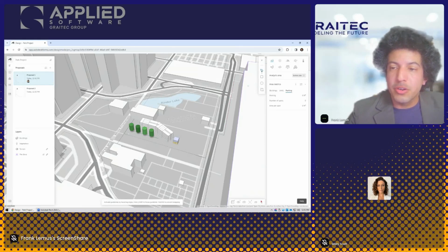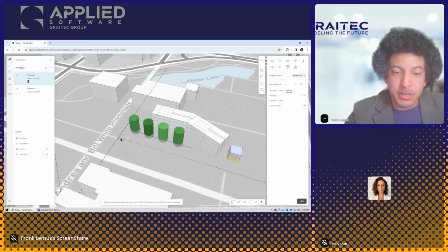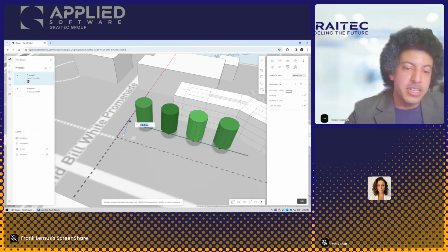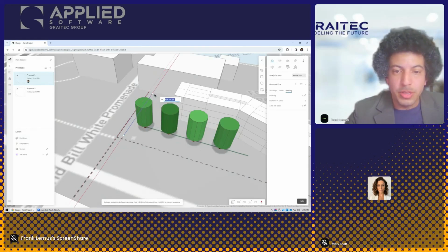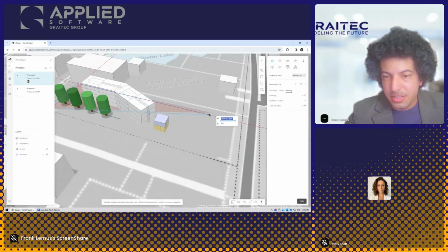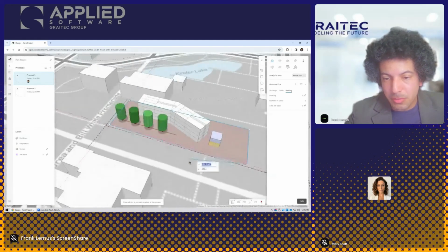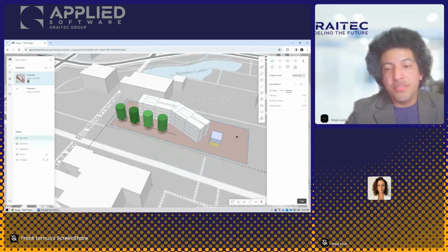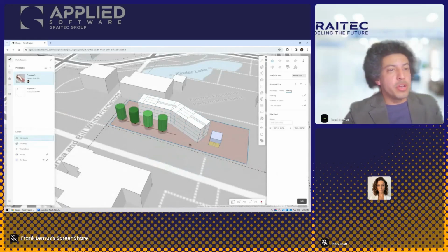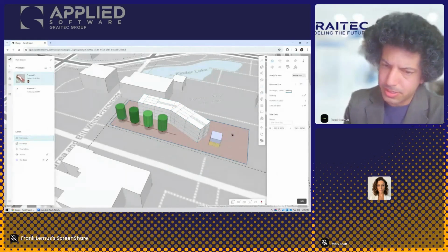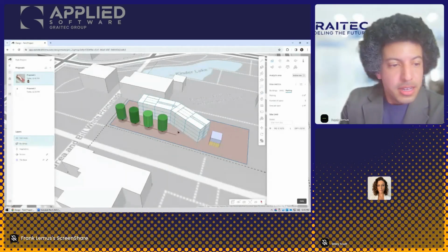Okay, I'm going to click on that, and I'm going to go ahead and create a freeform line. Let's just say I want to start from here. I'm going to hover over this existing line to capture it, and then I'm going to try to go parallel with it. Now I'm trying to work in 3D, so forgive me if I get this kind of sloppy, but you see what I'm doing here is I'm using the geometry all around, and then once I'm done, I'm just going to hit enter, and now I can hit escape. And I have now defined an analytical area, or what we call a site plan, or a site area, or whatever, I'm not sure the official name, but that's what that is.